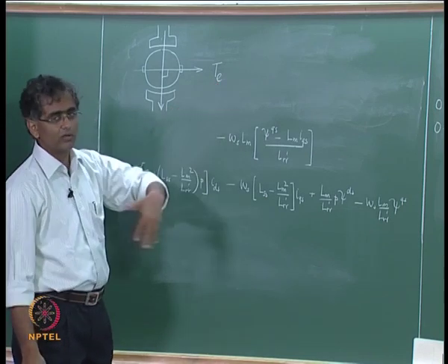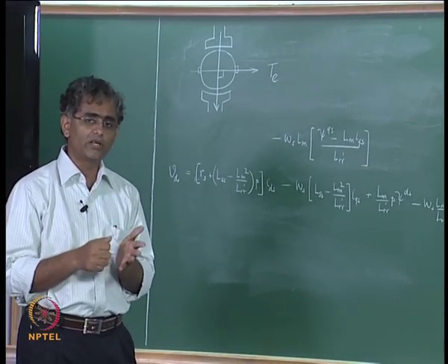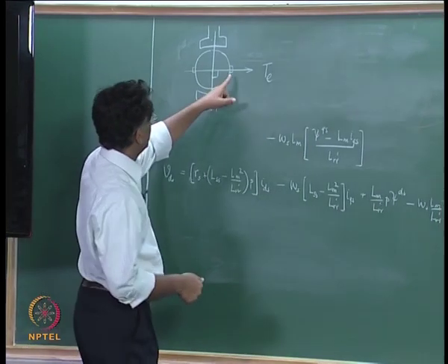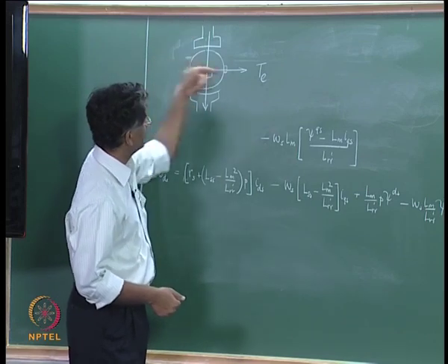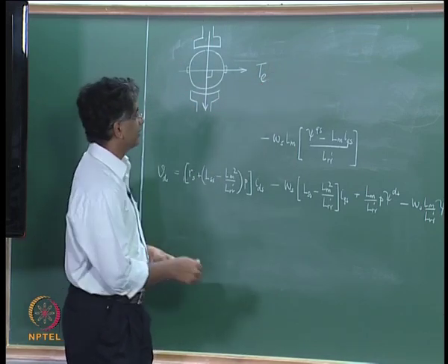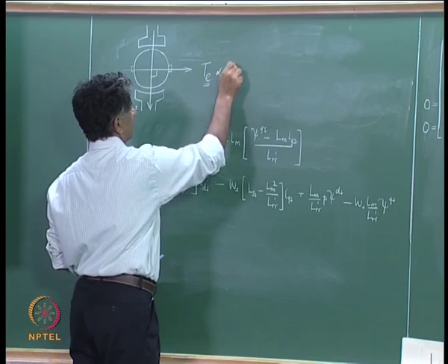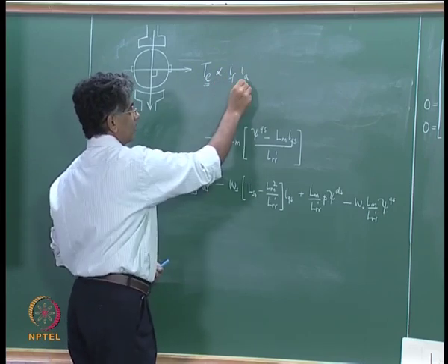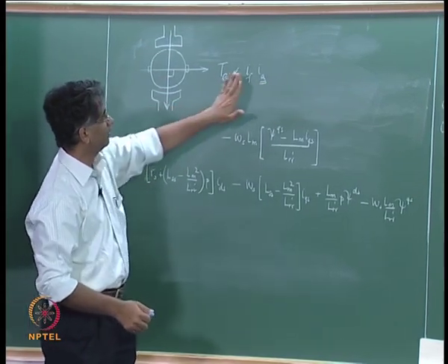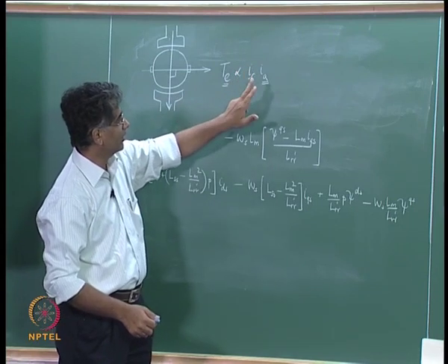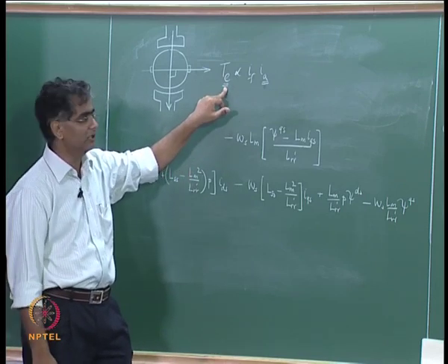is, if you remember back the DC machine equations, a mutual inductance multiplied by the field current multiplied by the armature current. That is true because the field current is producing a field in this direction, armature current is producing a field in that direction, and therefore if you want to control the generated TE, since it is proportional to IF and IA, you can control IA alone independently, and since IA does not influence the main field, you can keep this IF constant. As soon as you change IA, immediately it will reflect on the generated TE.